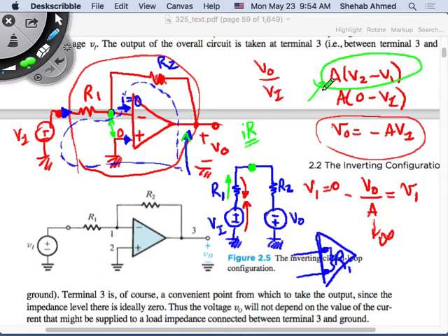This also happens to be a nice linear circuit. Since it's a nice linear circuit, superposition applies. So if anything else is causing something to be at the output terminals, then the output will be some value. This is what we constructed by adding components around it. We made the output affected by things other than the open loop gain. These resistors, and maybe capacitors later, are put around it, and they benefit from the properties of the op-amp, having infinite open loop gain and infinite input impedance, such that no current is flowing here.